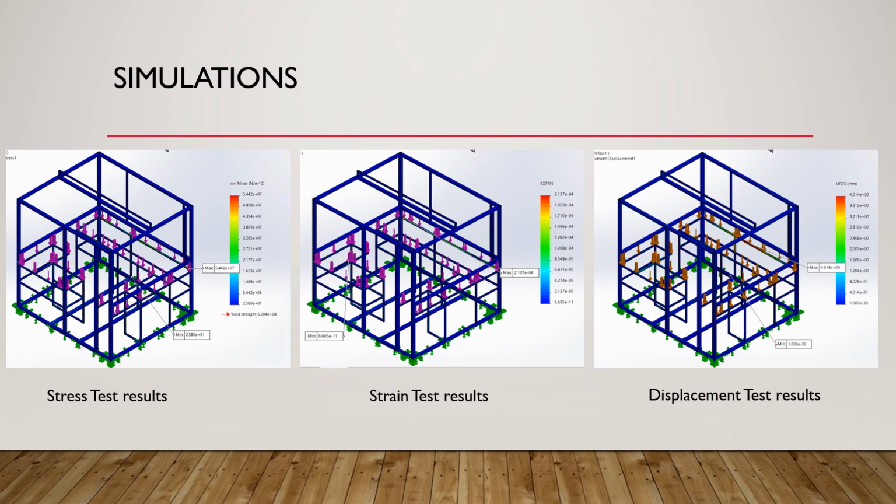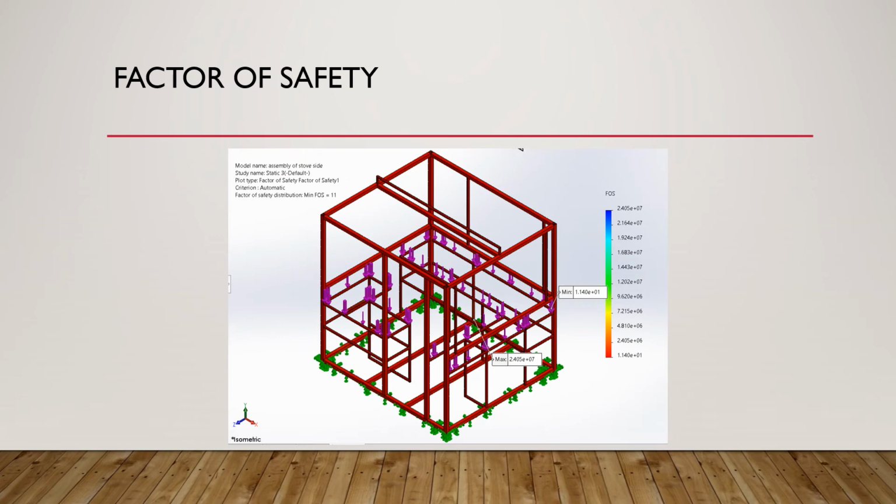Simulations are run using the maximum remaining weight that the cart can uphold, assuming that all this weight is due to appliances which should be placed on the counters. This weight is 700 pounds, which is over the recommended amount for a countertop to withstand. All 3 tests show that the internal frame was well designed. Simulations also produced a factor of safety for counters. This was found to be 11, which shows the design can be optimized to save material and therefore cost.